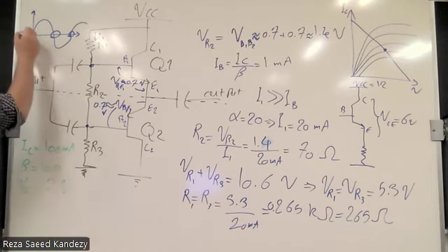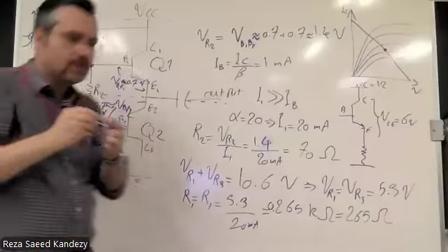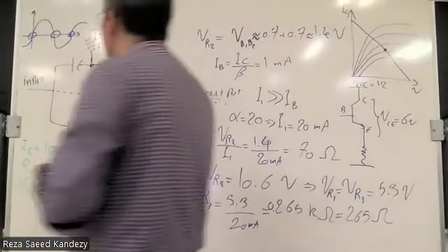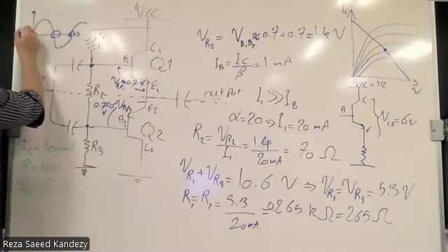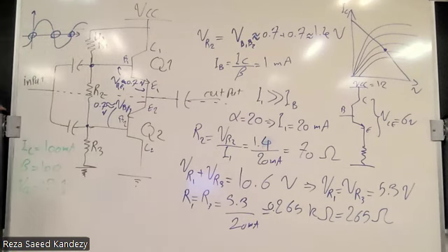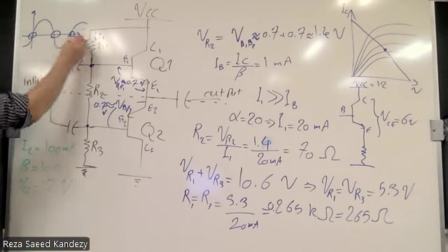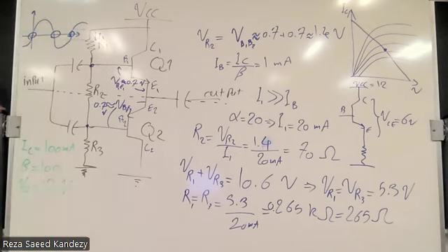Okay, so let's say this is the line. Let me choose another color. Let's say this is the line of threshold. Now we have two transistors, NPN and PNP. One of them works in the positive, another one works in the negative. So we have two threshold lines. Between the two lines, none of the switches are on.